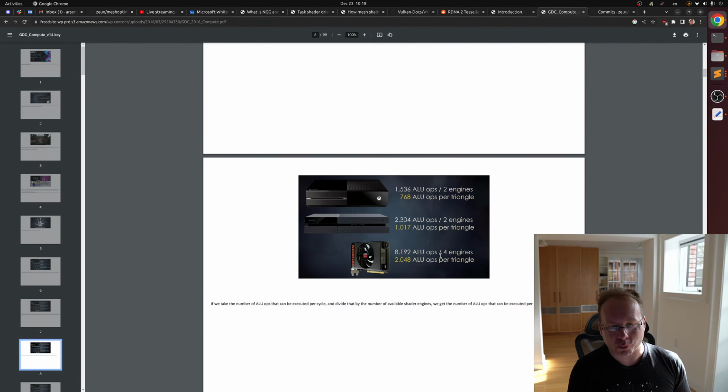essentially, while the fixed function unit that culls geometry or that renders triangles, I think in this case the one that culls triangles. So there is a hardware unit that also can do backface culling and probably triangle rejection for triangles that are too small. So it can do 4 triangles per cycle. We can do 8,000 ALU ops in the same amount of time.